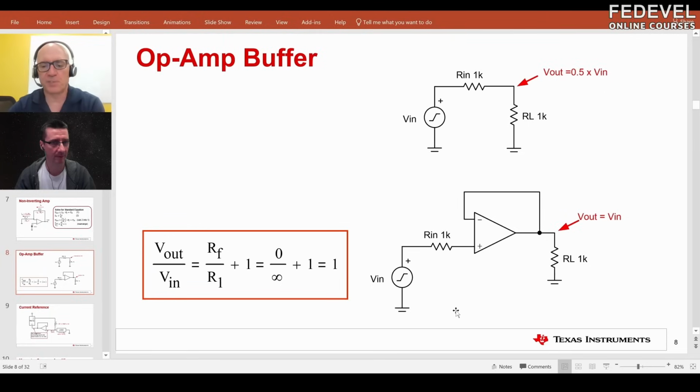So often people say, well, why do you want to use an amplifier if its gain is only 1? The input is equal to the output, the output is equal to the input. So why bother having the amplifier? Well, the reason is our sources will have some impedance. A source could have an impedance of single ohms, kilo ohms, mega ohms, even giga ohms, as we'll see later in the demo.